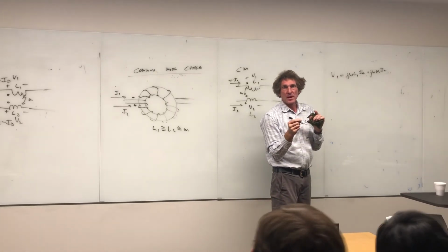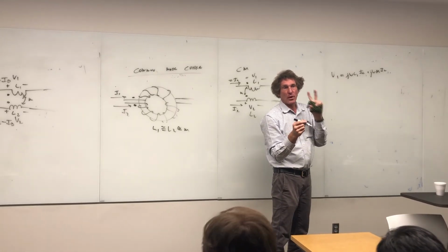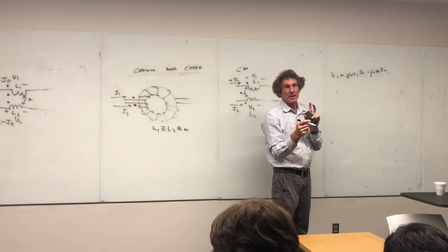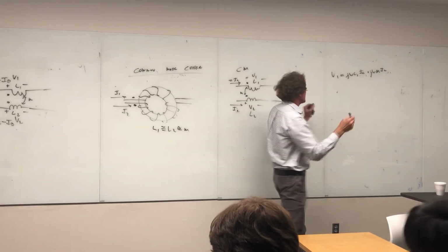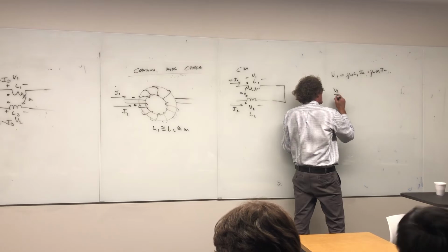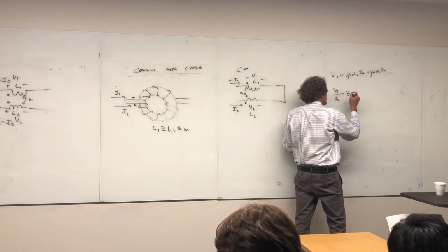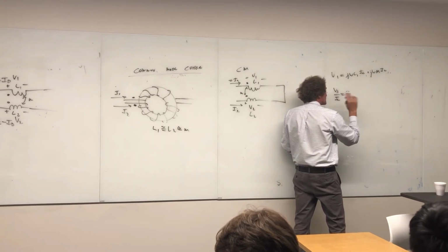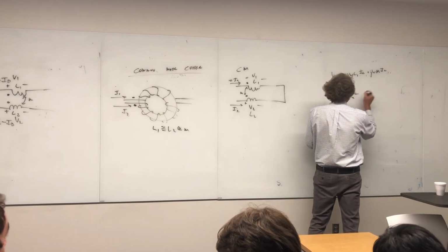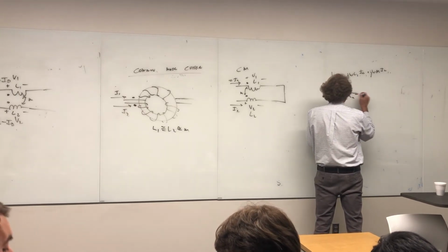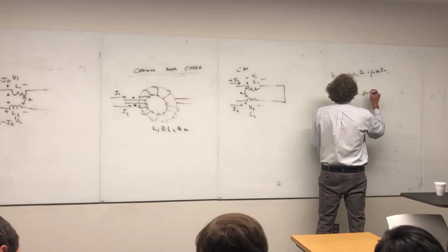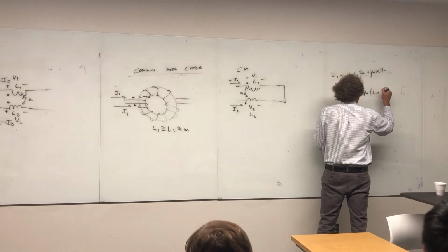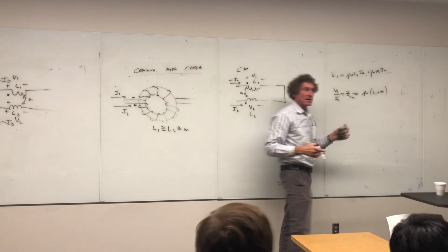Now watch. So what is the impedance of that coil where the voltage V1 is? If I look for V1 over I common, that would be the impedance of the coil in common mode. It's just one coil winding. Here, can you all see how it becomes just j omega, and then it's L1 plus M. You all see that?